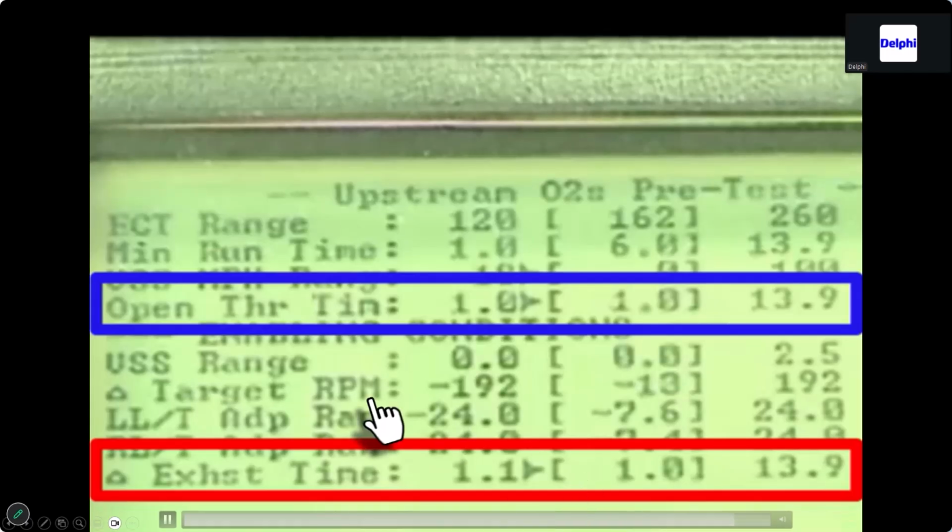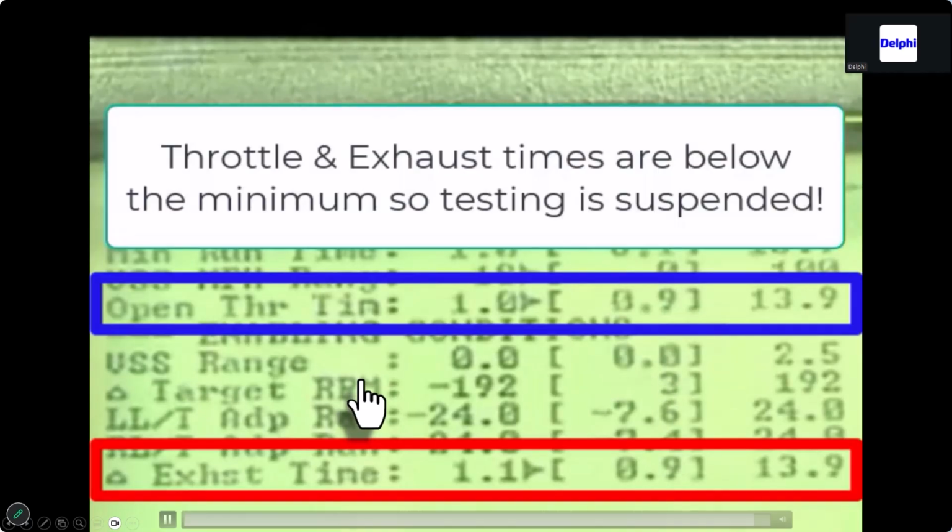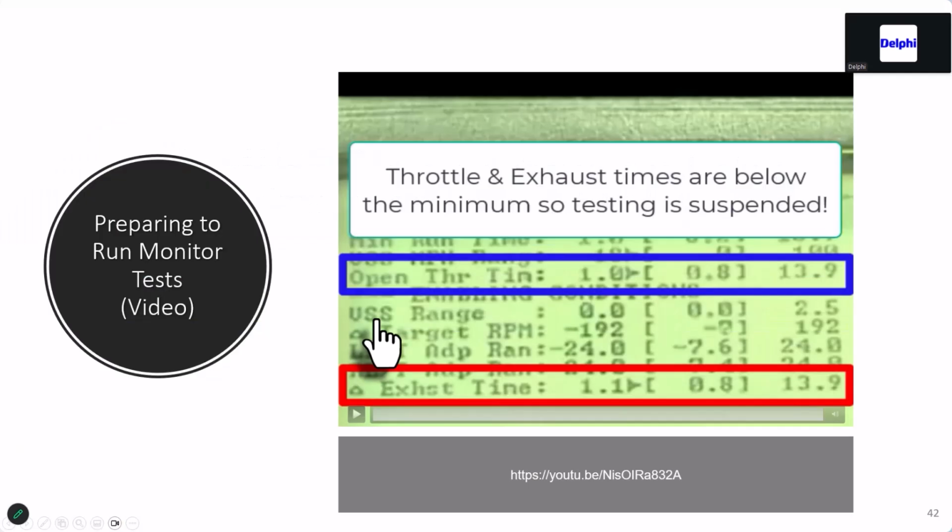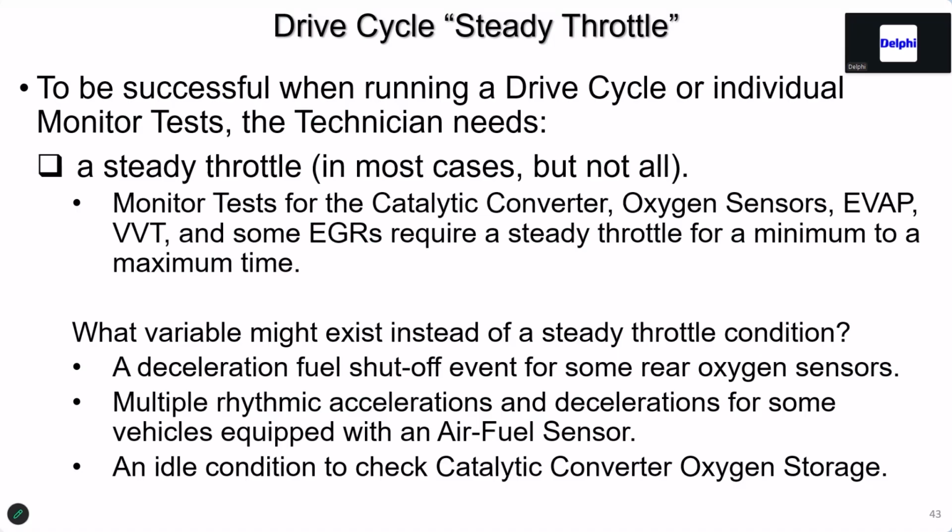This is what you would do to say, hey, the exhaust is hot. The PCM does the same thing. If the exhaust is cooling down and you see the global CAT temperature dropping, then you've got to wonder, are we cooling this exhaust down? Are we wasting our time? Should we shut it down and restart it? Now, those videos are also on my YouTube channel. You can get them through my website.